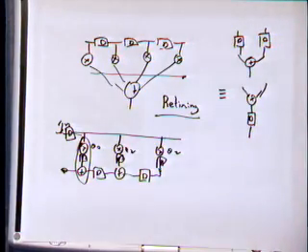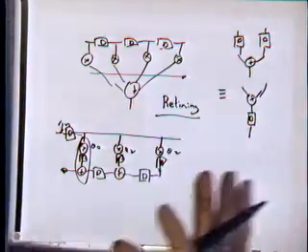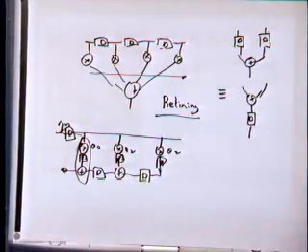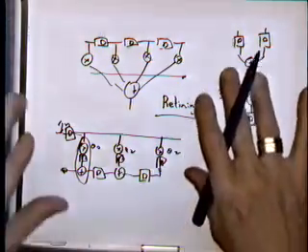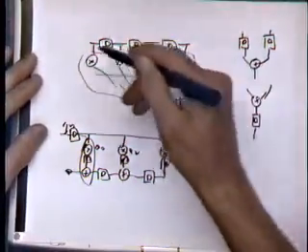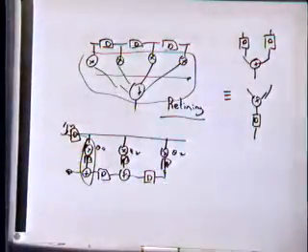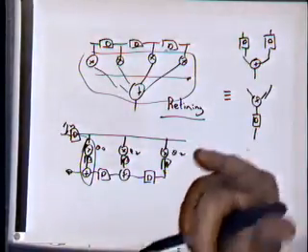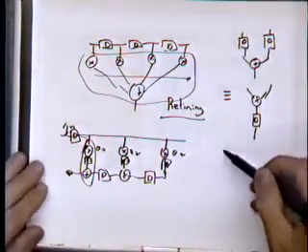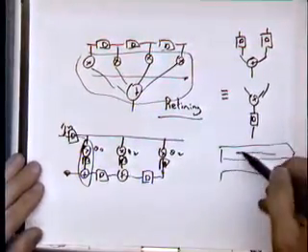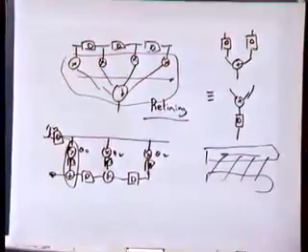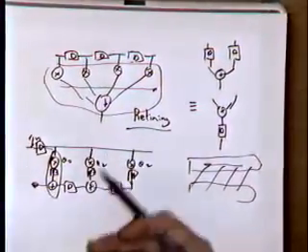Okay? So that was one way of approaching it, which is really restructuring this thing very carefully. And as I said, a lot of you have really done this almost to optimal end. Basically, 2 additions in a row is what a lot of you came up with. The other part was to say, well, gee, I'm going to look at the multiply-add structure, what I have here, which is adds and shifts, and really do a very careful manipulation of how I forward the data through it. So one option is to think carry-save. Move your carries in a different way. Instead of having your adders like this, now move the carries horizontally or diagonally, like we did in a multiplier.